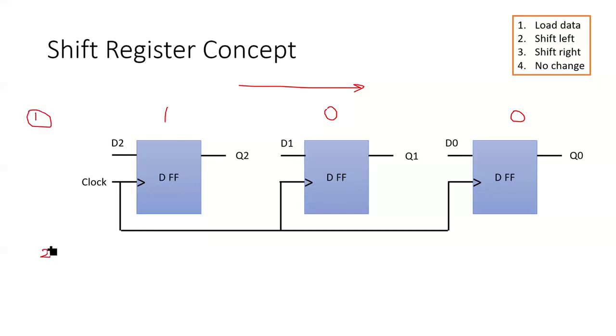In the second clock cycle, you should see 0 because there is nothing on the left hand side. And then this 1 should appear here. So 1 and 0. In the next clock cycle, it should shift even further. So you will get a 0, 0, and this 1 will appear here, right? So you see this is a shift right operation.